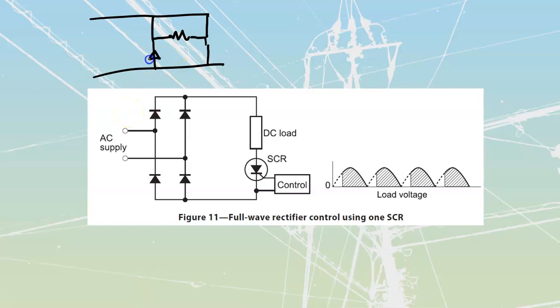And then I'm going to have that, and then a corresponding one like that. And then for the opposite side over here, I'm going to have this. And then let's do that one in the wrong direction there. This, like that. Right now I'm just drawing only the diodes, but if I have a positive, negative, I would see that this one would be conducting, because it's positive. This one would be blocking, because I've got a negative applied to there. This one would be conducting, because I've got a negative applied to there.